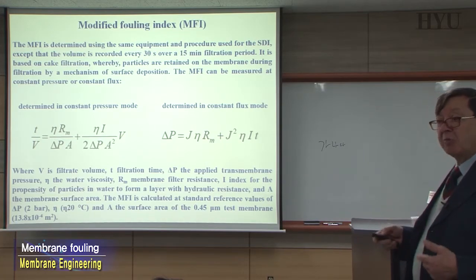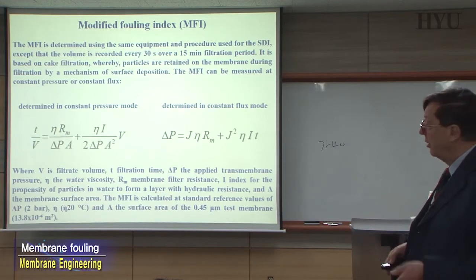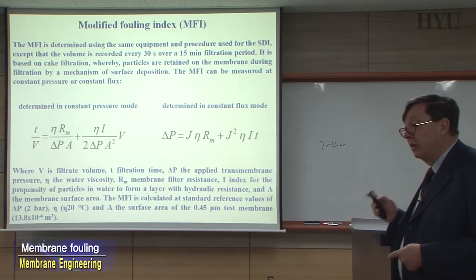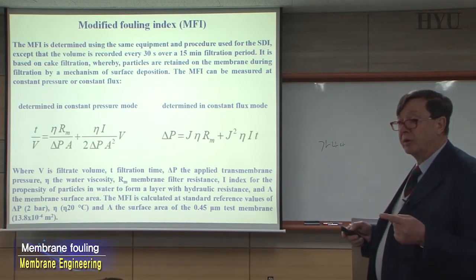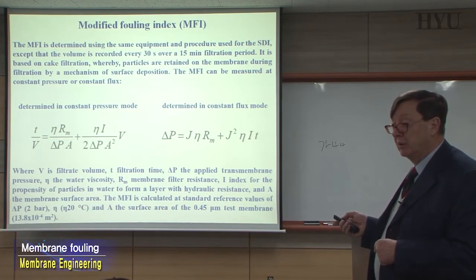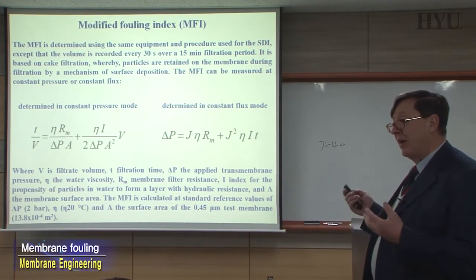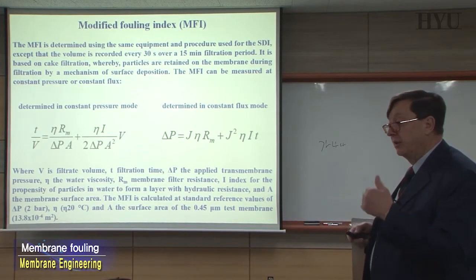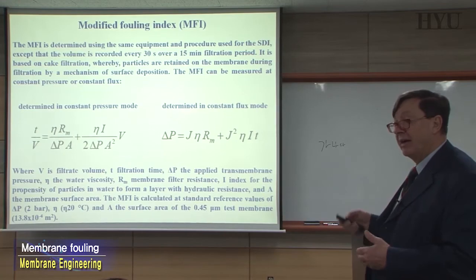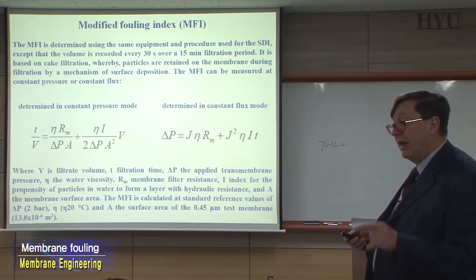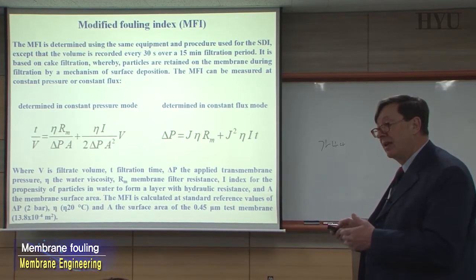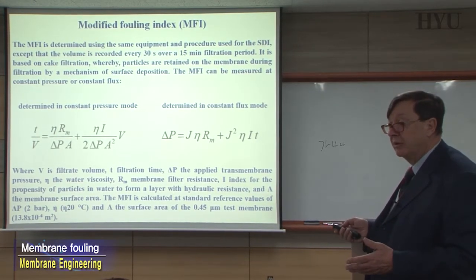All our systems normally are working cross flow. Second, we are learning that the particles at the origin of the problem can be much smaller than the ones going across 0.45 micron membranes. People were assuming that the origin of the fouling was mainly related to particles of a certain size, protein, polysaccharide, etc. It is not. Today, the microorganisms, particularly the first bacteria, etc., can be particles totally different, of very small